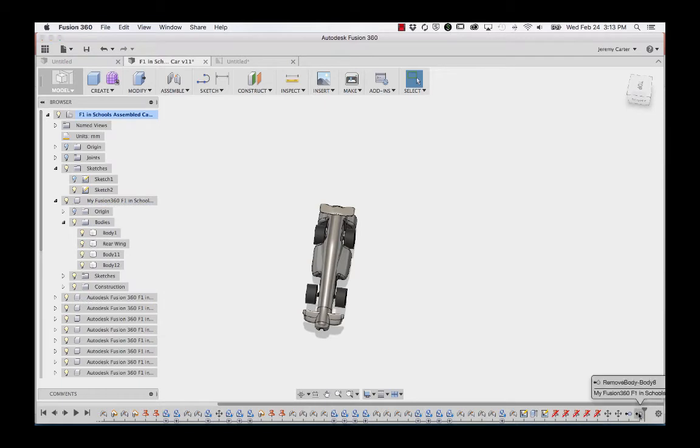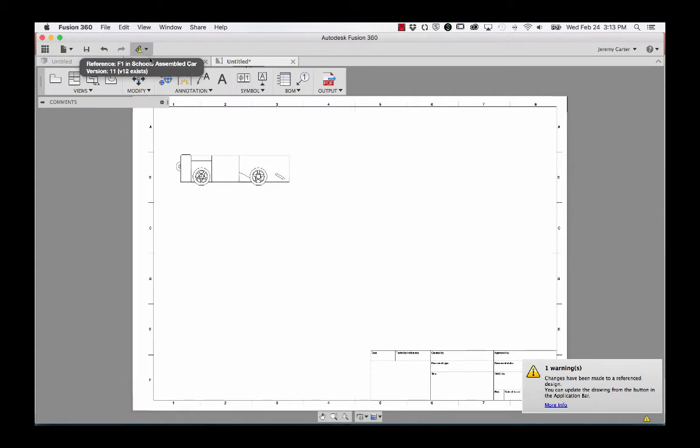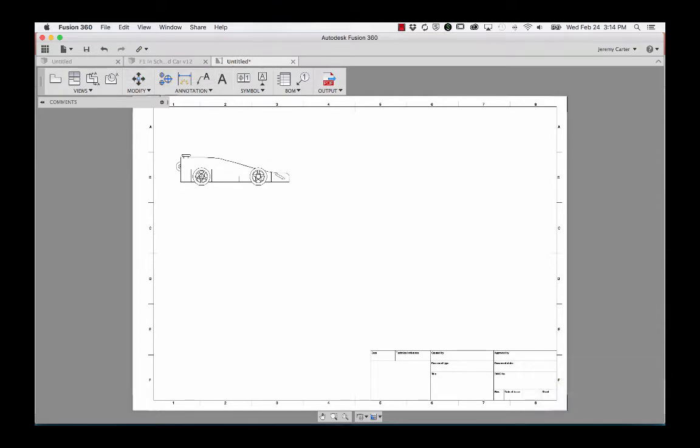This instruction will show in the timeline at the bottom and can be scrolled back at a later time if required. Just drag the end stopper to before either of these two icons. Click Save and OK. Now return to the drawing window. You will notice a yellow triangle on the toolbar. This means a change has happened and the current document is not up to date. Press it and get Latest. All your assembly will update with the changes you've just made.